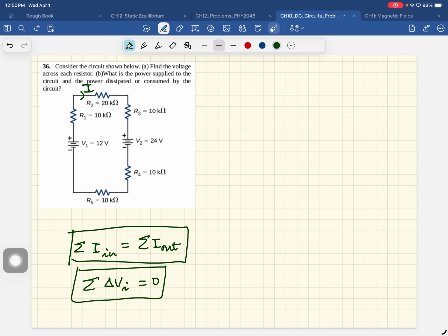Now we've labeled the direction of the current to be that. Obviously we know it's wrong because I've already told you the current is going to be flowing in this direction. Now if you set up the equations assuming this direction as the current, the current will come out to be, let's say, minus 5 amps. What does the minus tell you? The negative sign tells you the current in the real circuit is flowing in the opposite direction. That's what it's telling you.